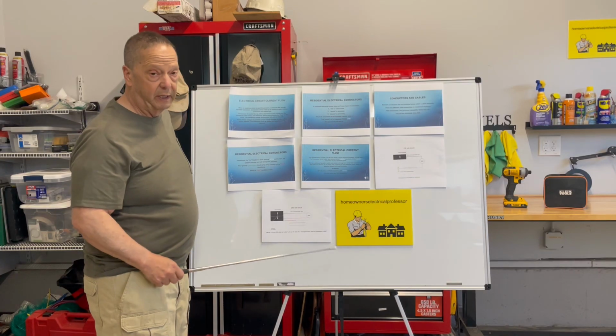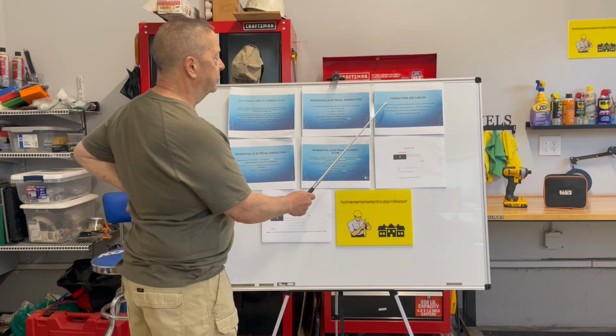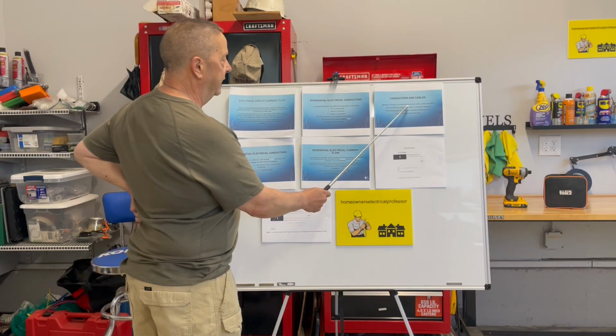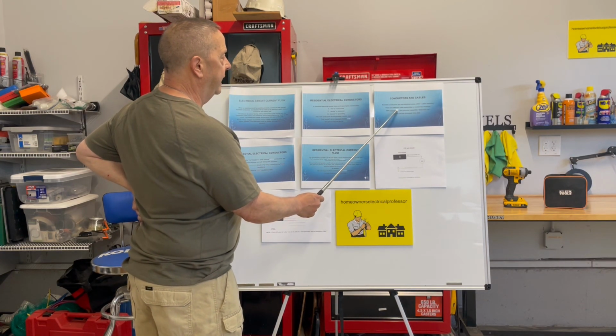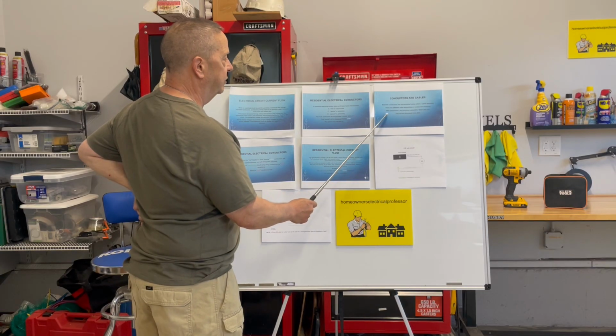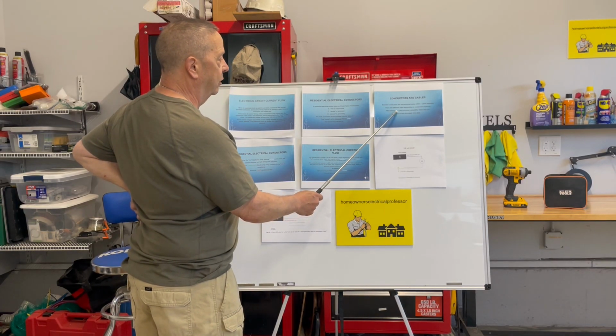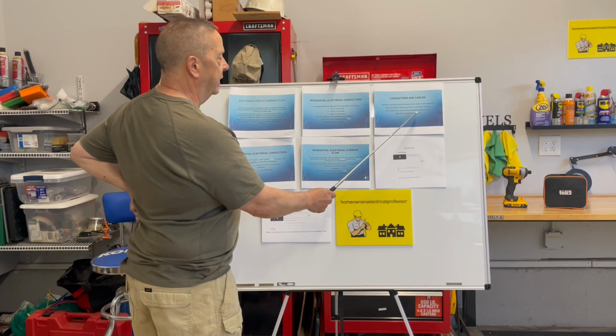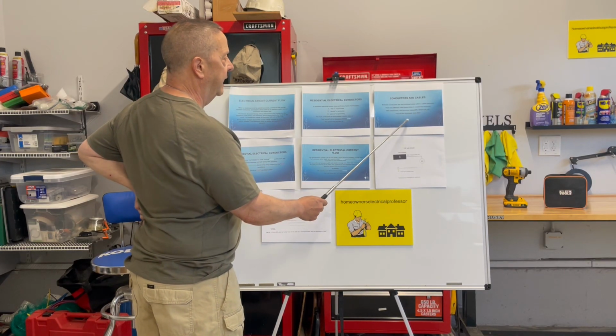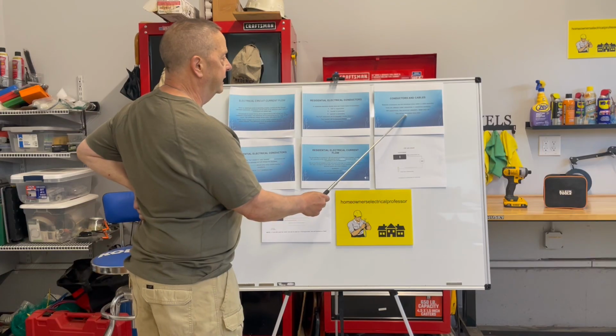Now, conductors and cables. Basically, conductors are the individual wires within a cable assembly. There are different cable assemblies in residential electricity. There's NM cable, it's also called Romex or Flex. There's armor cable, sometimes called BX. There's metal clad cable. This will be discussed more later.